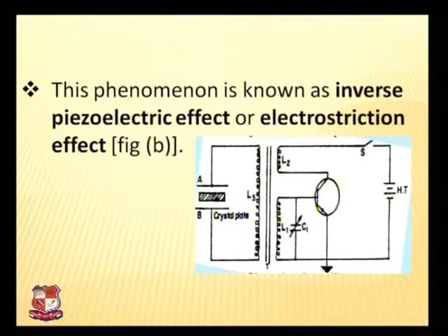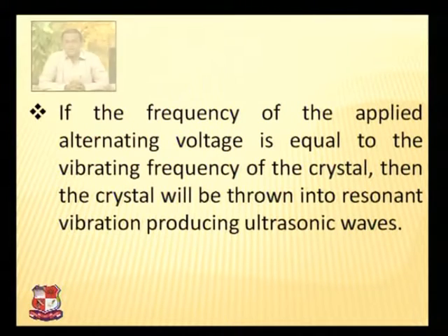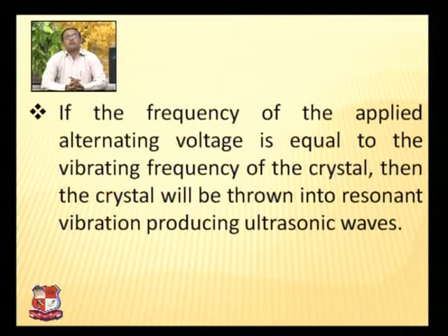of an ultrasonic production method, the piezoelectric effect, which is based on the inverse piezoelectric effect principle. In this figure, you can see that if the frequency of the applied alternating voltage is equal to the vibrating frequency of the crystal, then the crystal will be thrown into resonance and the vibration produces an ultrasonic wave.